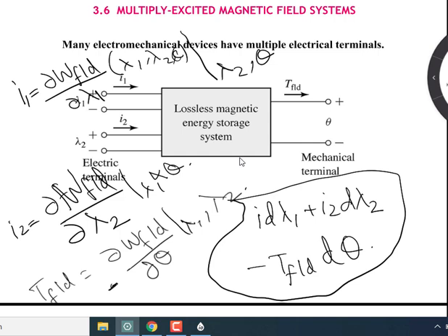If we do not want to corroborate with energy conservation, then we can drop this negative sign, and it would indicate that if you produce more output from your system, or extract more output in the form of mechanical energy, your magnetic energy reservoir energy will also rise.